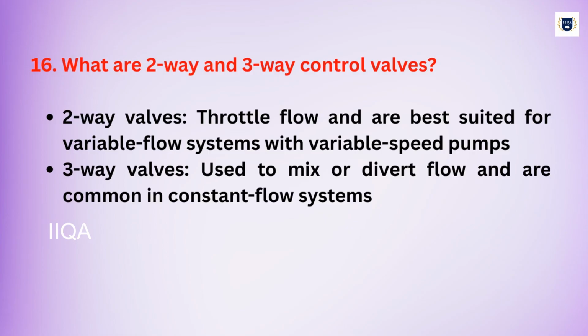What are two-way and three-way control valves? Two-way valves throttle flow and are best suited for variable flow systems with variable speed pumps. Three-way valves are used to mix or divert flow and are common in constant flow systems.